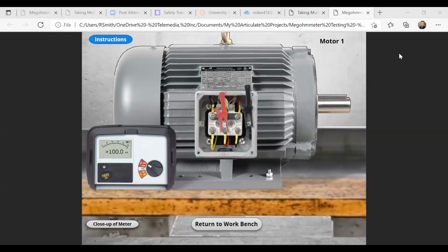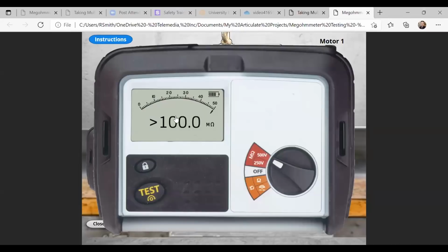Let's see, if an HVAC compressor is shorted to the ground, right? How would the multimeter read? And this is actually to really find a ground fault. What you're seeing here, this could be a compressor motor for all we know, a 3-phase motor. Looking at the metal housing with one lead and one of the phases of that motor with the other, and we do the mega test with the testing button, and we get a reading that's less than 5 mega ohms, or something just small enough that this mega ohm reading is small, that starts indicating we're getting that ground fault circuit issue there.